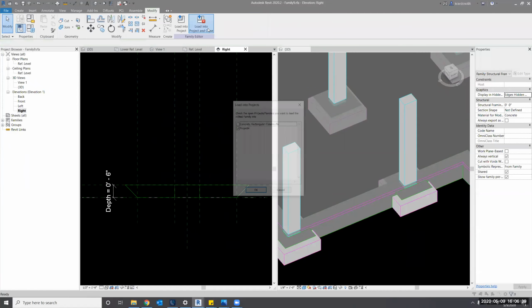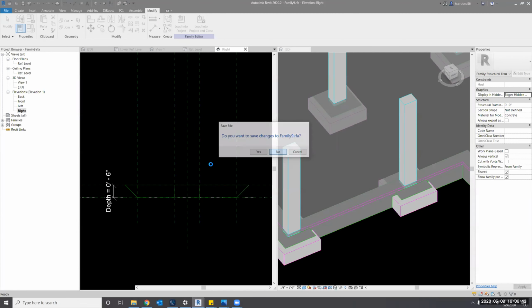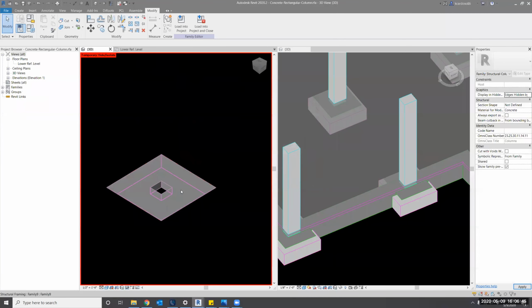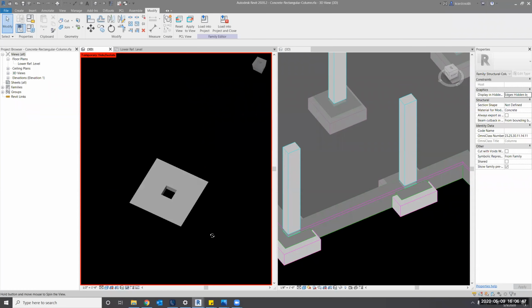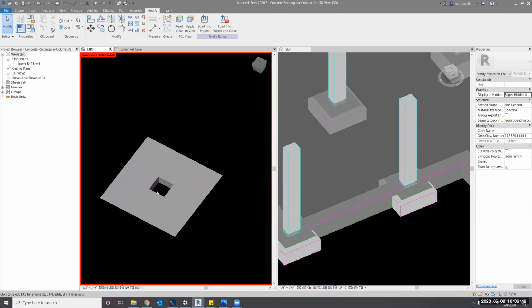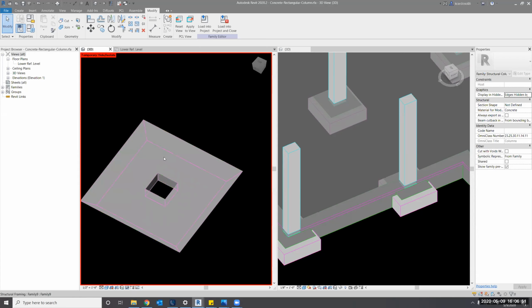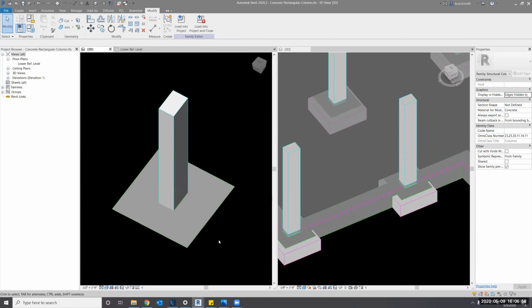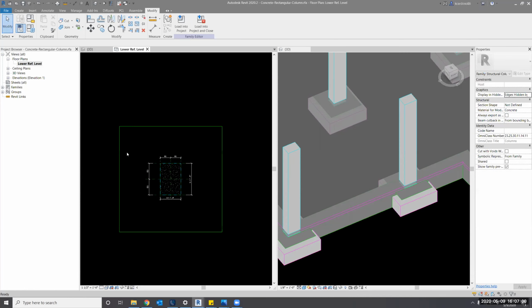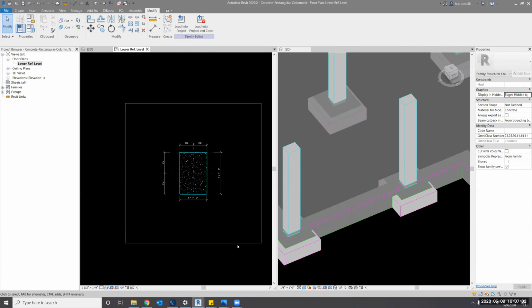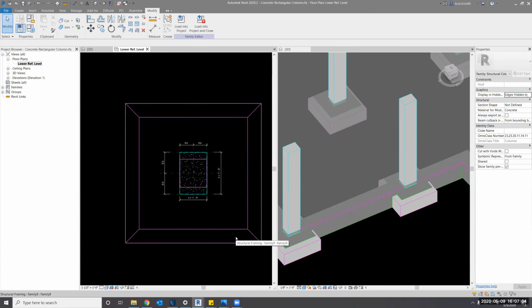All right, let's load into project and close. Let's go into our column. We don't want to save this yet. We want to override this, and there is our hole. Now we need these dimensions to match the column that is going through here. So let me restore this view down here, reset. And let's go to a plan view, because in that case it is easier to see. If we hover over the thickening, we can see it doesn't match.